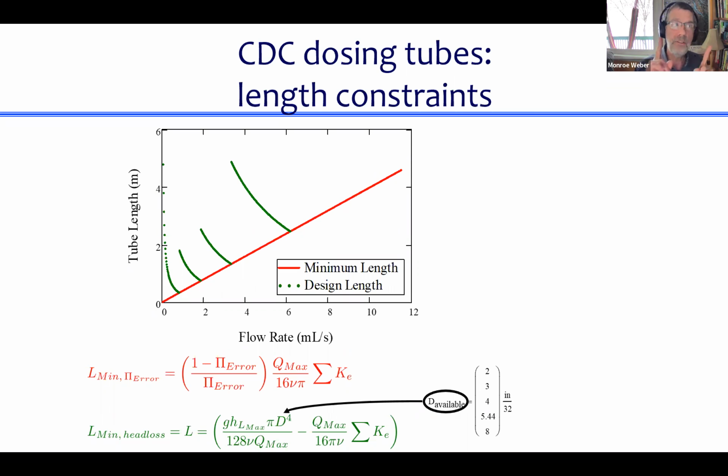Right? If I increase the flow, but I want to get back to the same head loss, I could just make the tube shorter. Do you buy it in that direction? Okay, and I was just saying it in the other direction. In order to get the head loss, I have to make it longer if I have a low flow.